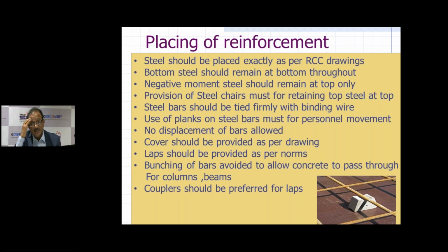And imagine, in a huge project there will be lakhs and lakhs of laps to be provided, and how much steel we are wasting. If we provide couplers, we will not only save the steel that is wasted in the laps, but we are also using couplers which allow us to freely place the concrete in the section without any segregation. So that is very important.